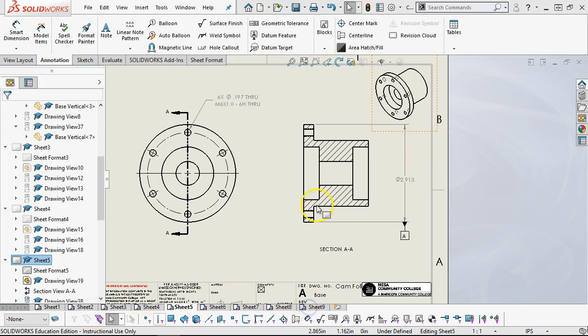All right, and the last one, the shaft. So the spherical diameter, nothing really clear here, probably because this is moving up and down inside of that bushing. The main call out here would be to establish the form tolerance of the cylindricity. So circularity, cylindricity, and if we, did I jump over it? Yeah, probably. Yeah, let's give it 2 thousandths. Yeah, fine, so .002.